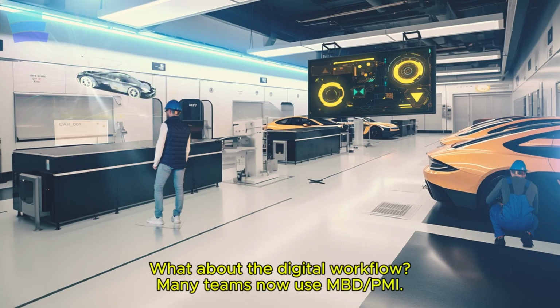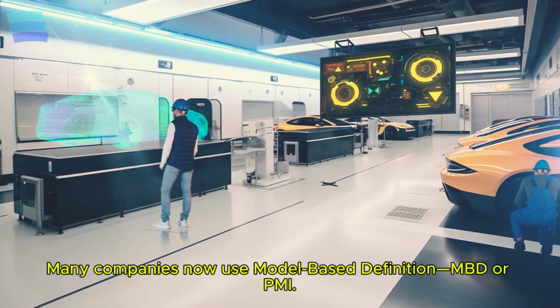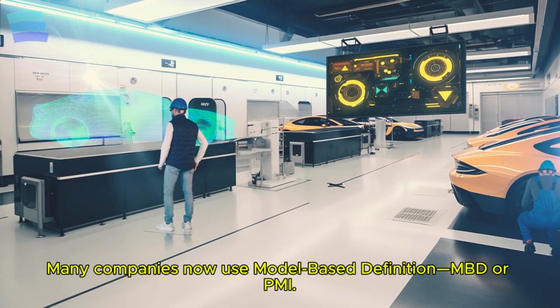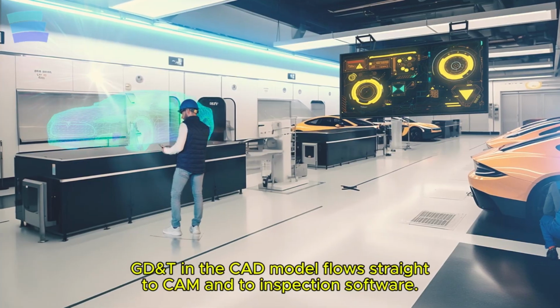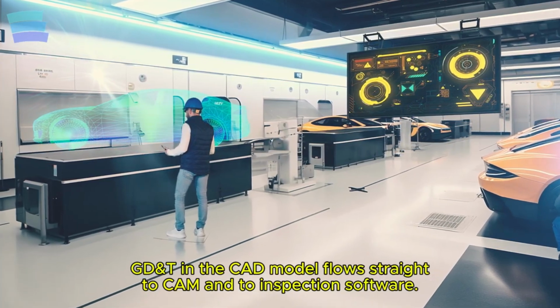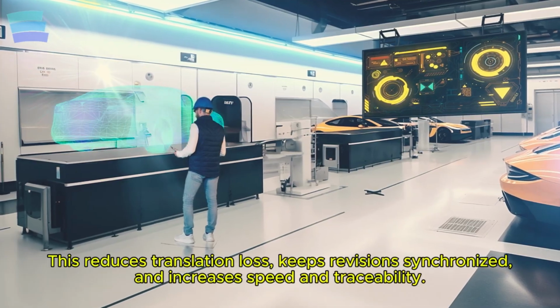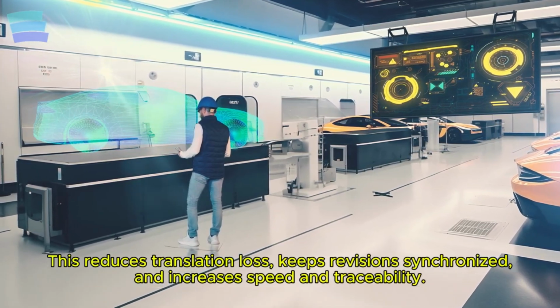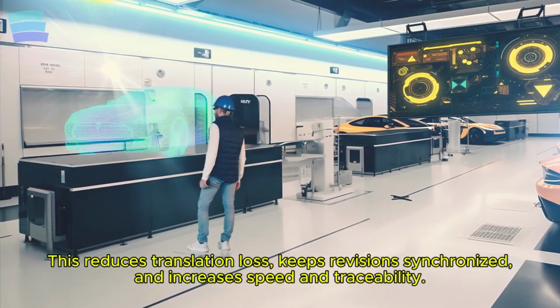What is the place of GD&T in the digital workflow? Today, some companies use model-based definition, MBD/PMI. Symbols embedded in the CAD model flow directly into manufacturing and inspection software. This reduces information loss during handovers and keeps revisions in sync. Digital traceability increases, and both speed and consistency improve.